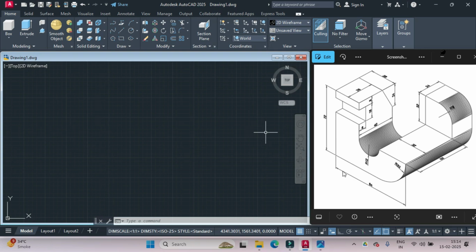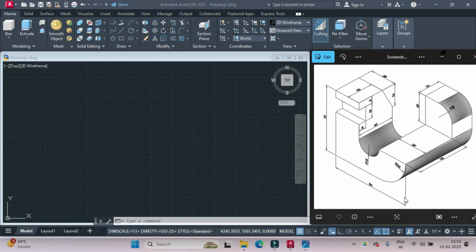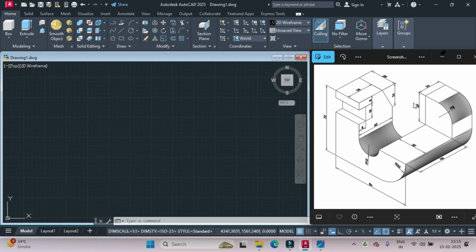This is the left view. And over here we'll begin drawing the profile by using the PLINE command, and we'll draw one line from here to here of 28 units, then from here to here 72 units, from here to here 84 units, and from here upward, that is 32 plus 32, 64 units, then to the left 32 units, down 32 units.